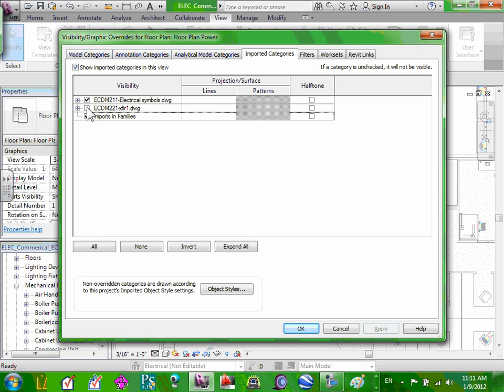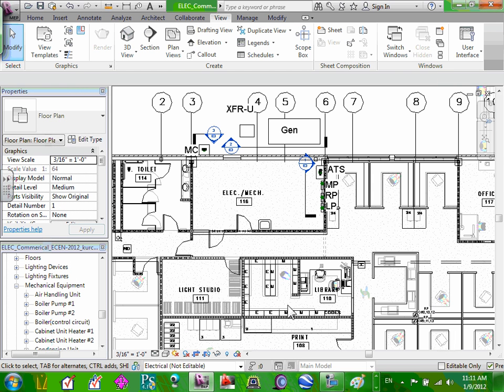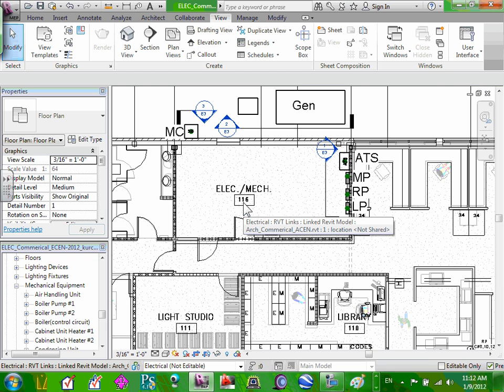All of you guys have imported the CAD view to show the rooms. I want to click on my imported category, the floor, just to see. That allows me to show the names of the rooms in Revit by clicking on the image that came from CAD. When I'm done with it, I can delete it. Okay, everybody see we're 116 here, right?